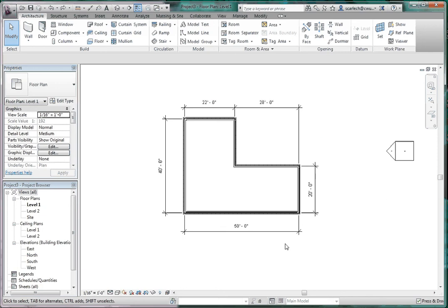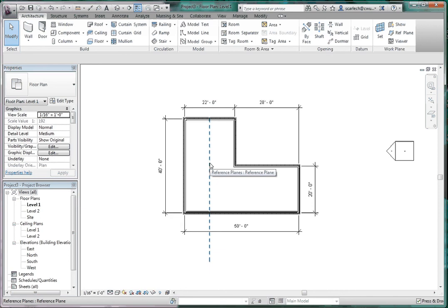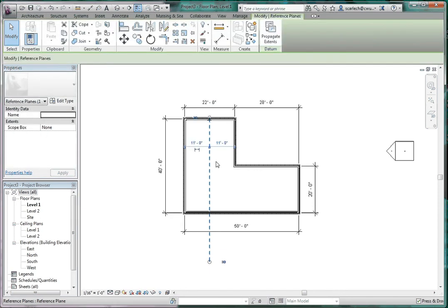easier to model. So let's say we want to insert a plane in here, just like the book showed. And the desire with some of these planes is to be able to put in some elements in here that can be mirrored from one side to the other, specifically walls, like if you want to do a hallway. So it's difficult. I mean, you can pick up midpoints of walls up here, like the book suggests, and then put a plane down here. But the problem with the plane right now is it's not defined at all. You can still move it around. So let's do Control Z.